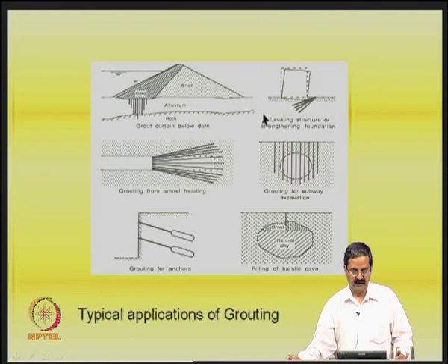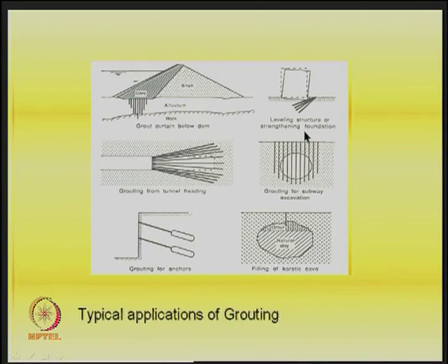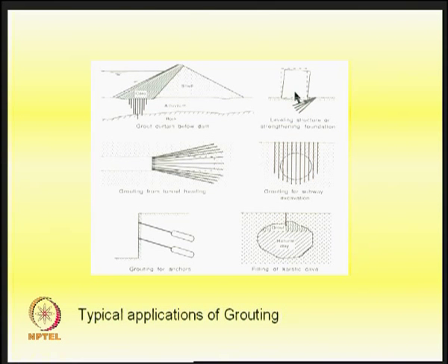Then the other one is leveling structures or strengthening foundations. For example, there is a possibility that foundation tilt is there, so you would like to stabilize it. So you put some sort of grout injections into the system so that it will not get damaged further.